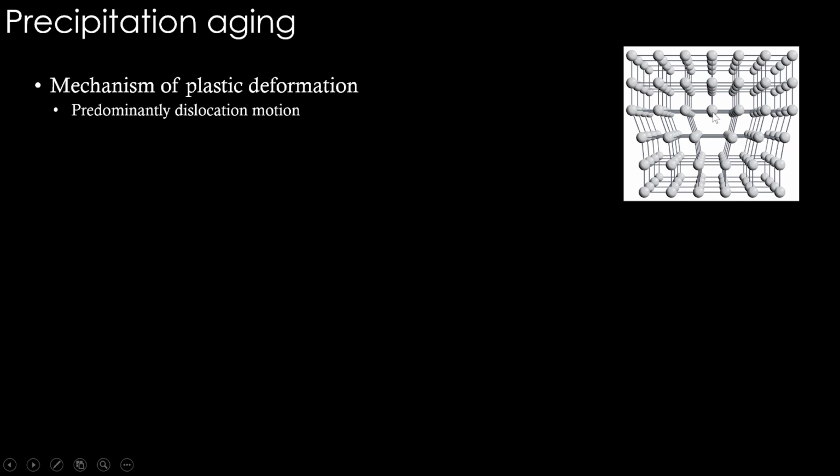Now if you look at this atom here at the bottom of this plane, below this there is no atom to bond for this. So this atom is not in its most stable form, and in fact the entire line of atoms behind that, just like this line of atoms, there is a line of atoms behind this atom, that entire line does not have atoms to bond, below. So the atoms behind this particular front atom, the entire line of atoms do not have atoms to bond on one side. Therefore, this line is a defect. This is a line defect. We call it a dislocation.